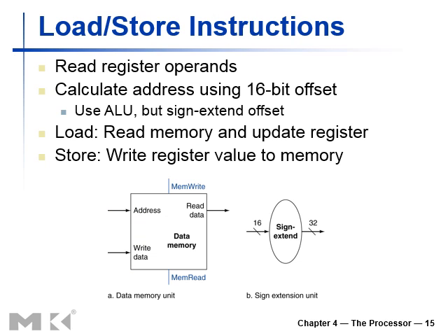Then for the load store instructions, we've got the memory compartment that is basically in order to deal with the data references, that is a data memory. Similarly, these two are coming from the control unit. One for the memory read, when we have to read the memory, we have to enable this signal, and one for the memory write, and when we have to write something in the memory, we have to enable this signal. Basically, these are the control signals that are being provided by the control unit itself.